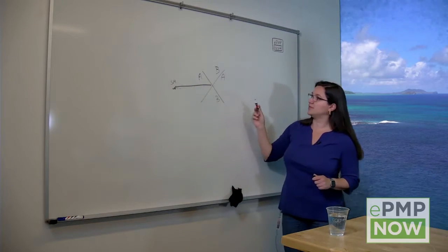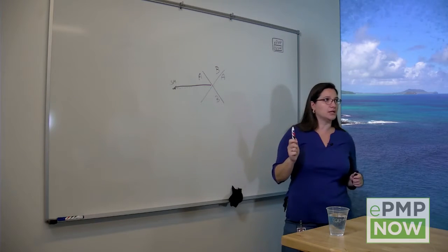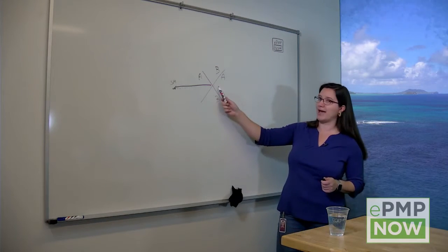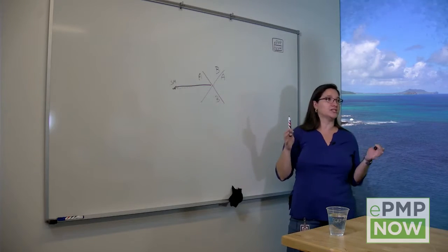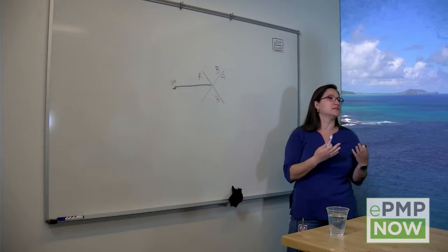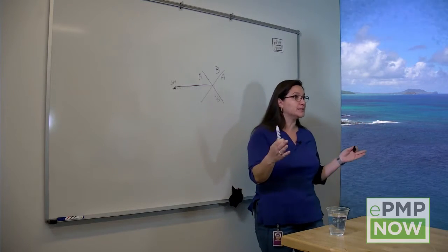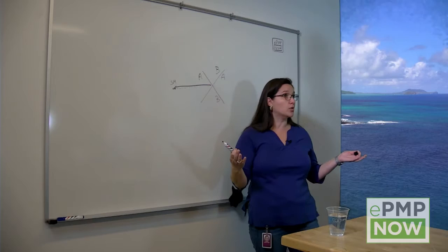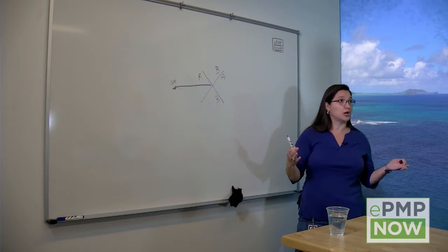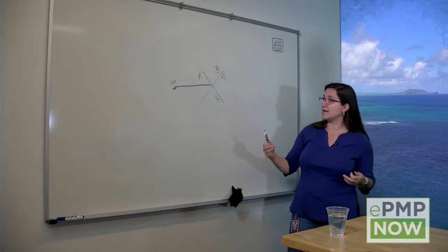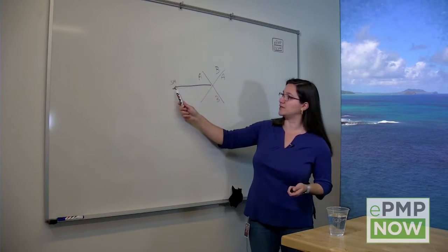Right. So the attenuation between the desired signal and the interfering signal is only given by the front to back ratio of the antenna, because the assumption is that the two antennas are co-located and there is nothing in between. Of course, if you had this installed on two sides of a building or two sides of a water tower, you would have enough isolation and additional protection because there is additional attenuation. But the worst case would be if there is no additional attenuation, and now this is your interfering signal.